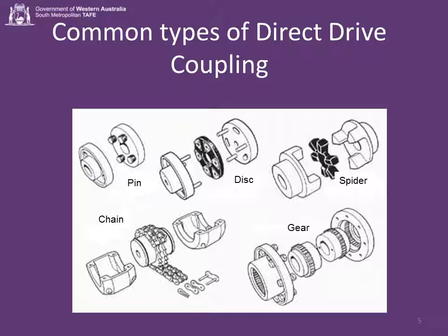Each coupling is connected rigidly to one of the two shafts by a key or some sort of contacting friction bush or by some other means. The motor and drive assembly is then adjusted to minimize the initial misalignment, then tightened down, and the half couplings are finally connected together by the flexible element.